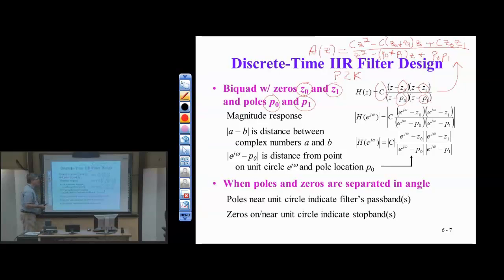All right, so again, we really end up with several degrees of freedom. Now we can go to a frequency response. This is fine in the Z domain, provided the poles are inside the unit circle, and that's the way we've defined filters, that they're bounded-input, bounded-output stable. So assuming the poles are inside the unit circle, we can make this change, Z equals e to the j omega, so that we can convert the transfer function to a frequency response, and take the magnitude of that to get the magnitude response.